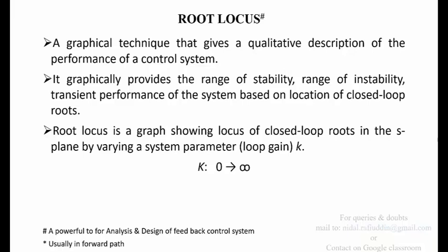Today I'm going to talk about the next part of this unit, that is root locus technique. Well, root locus technique is useful to aid control design and analysis. This in fact is a graphical technique that gives a qualitative description of the performance of a control system.